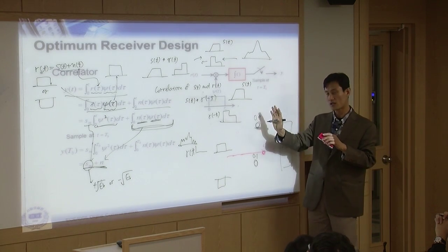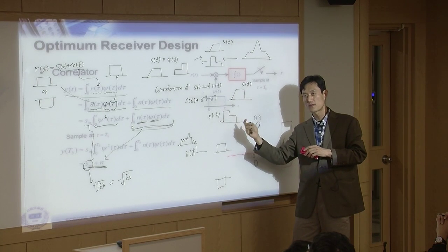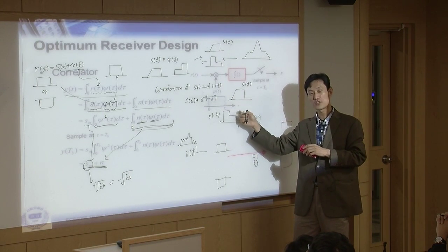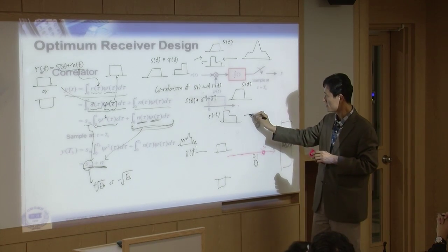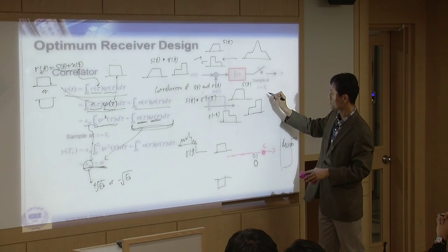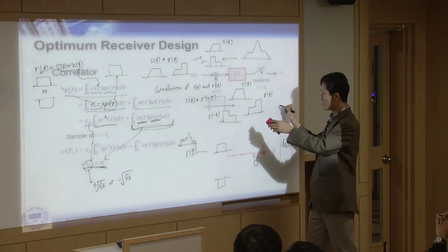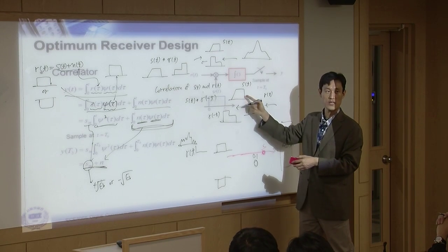I want to do convolution between these two. In that case, what do you need to do? You have to flip the second one, because for convolution of these two we flip this. When you flip this, it becomes that, and that is actually the original r(t). So it's a slide: you slide and calculate the correlation between these two.